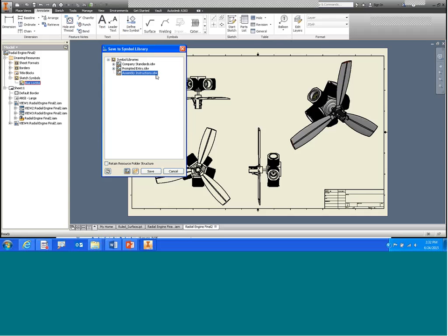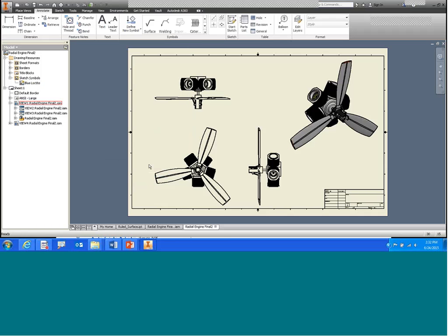And the first thing you're probably seeing is these are all IDW files, and that is exactly it. All the libraries are stored as IDW files in your design data folder. So you can go in and actually modify those drawing files and change them as you needed to. So I'm going to save my Loctite symbol into the assembly instructions and hit Save here.